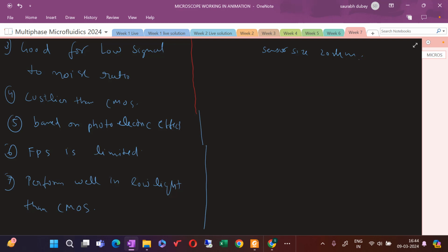It is the simple optical microscope illumination technique where the sample is illuminated from below and observed from above, or it can be illuminated from the top and observed from the top itself because of reflection. There could be any arrangement based on the upright or inverted microscope you are having, and the contrast caused by the attenuation of the transmitted light in the dense areas of the sample is responsible for getting the information about the sample.